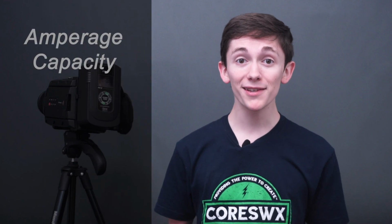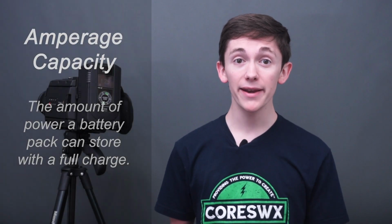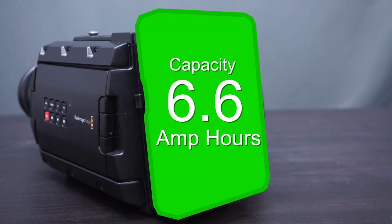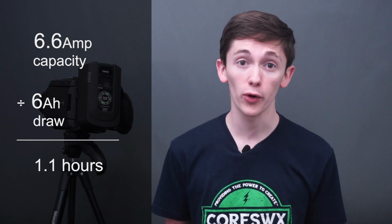First, the amperage capacity of the pack is how much power the battery pack can store. For instance, a 98 watt hour pack has 6.6 amp hours of stored capacity at 100% charged. This spec helps you determine how long a pack will operate your device or rig. If your rig draws 6 amps, then a 6.6 amp hour pack will power it for just over an hour.